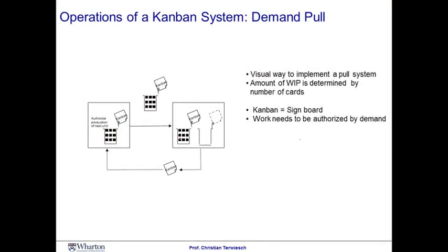To control the amount of inventory in the process, the Toyota production system has developed the concept of Kanban cards. Imagine we're selling these beautiful little black boxes to our customer, and the end customer demand is here on the right. We have an internal supplier, another department that supplies us with containers that include 9 of these black boxes. Once we have emptied one of these containers, we take a card, a sticker that is attached to the container, and we move that card to this department that is feeding us with the black boxes.